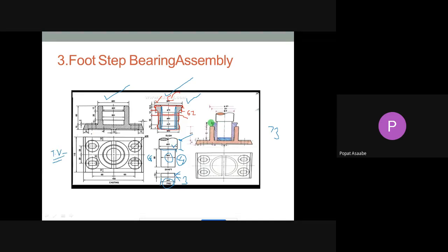What is meant by the top view? How to draw that top view? Just view from the top, and you have to remember the concept. Which line is visible? Draw that as a solid line, and which line is not visible? Draw that as a dotted line. Okay, see here, they have already given the top view. As it is, we want to draw the top view here.